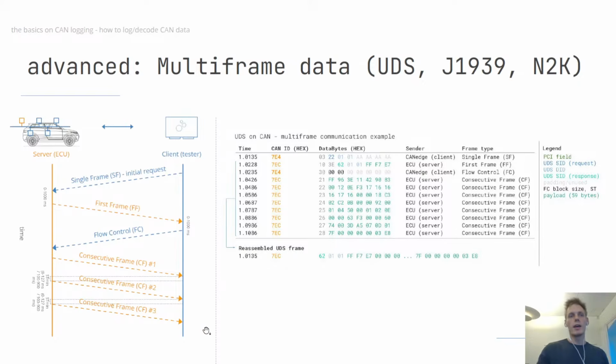The idea here is that this is a very efficient way of packing a lot of data because the car can essentially spam, let's say 20 frames in a row containing all sorts of data, meaning instead of being able to send one or two CAN signals, it can potentially send 20 CAN signals in one go.